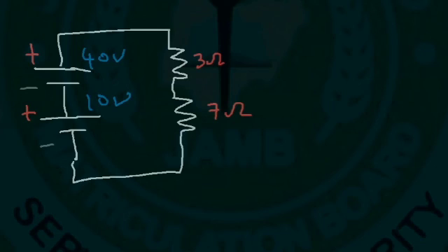When you connect the positive terminal of one battery to the negative terminal of the other battery, the voltages are additive. Both batteries are delivering power to the circuit. So both batteries are in discharge mode. They're delivering energy to the circuit, which means that they're losing energy. Over time, the batteries will run out of juice.